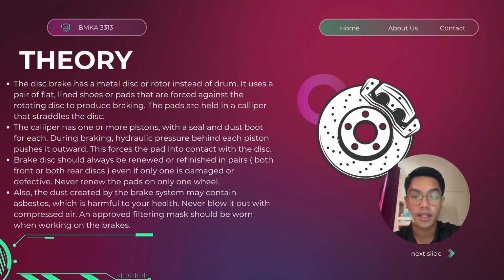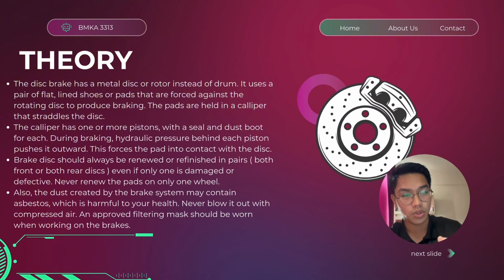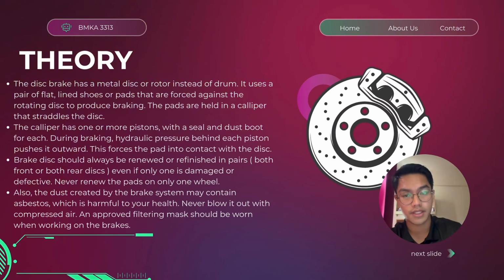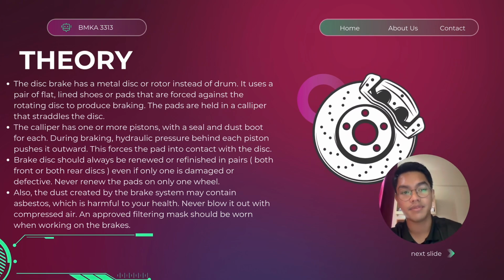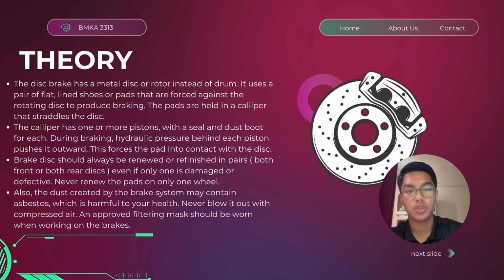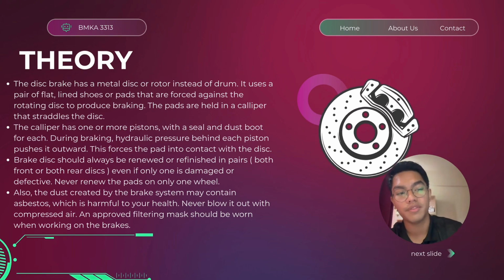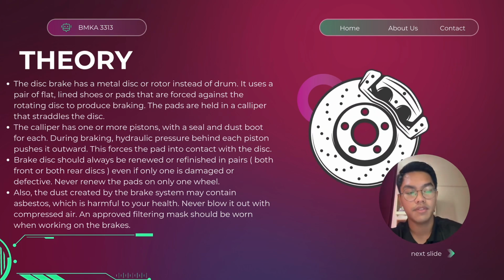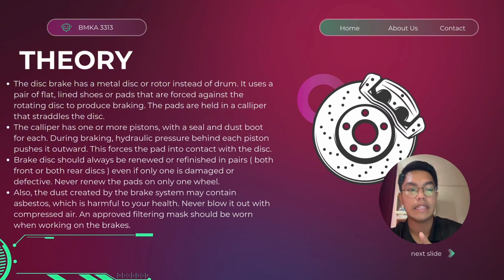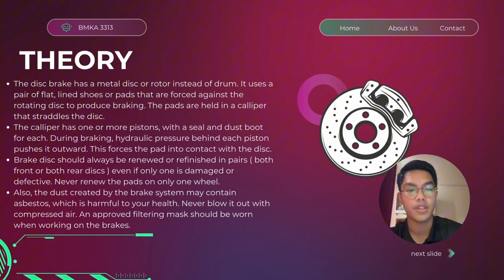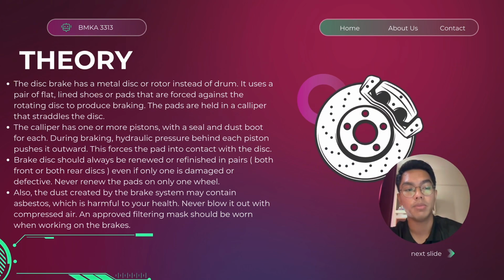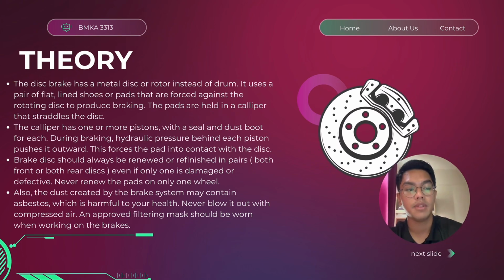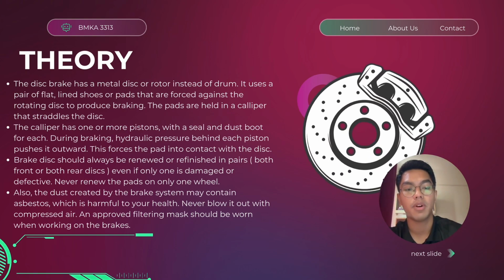vehicle. It is important to note that when servicing brake discs, both discs on the same axle, either the front or rear, should always be renewed or refinished together, even if only one disc is damaged or worn. Similarly, brake pads should be replaced on both wheels at the same time to ensure balanced braking performance.